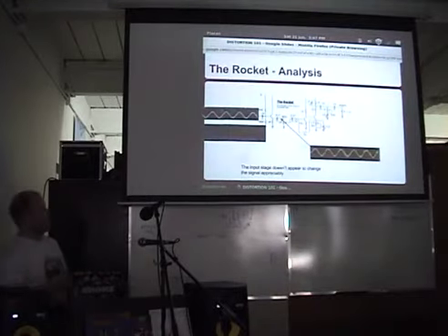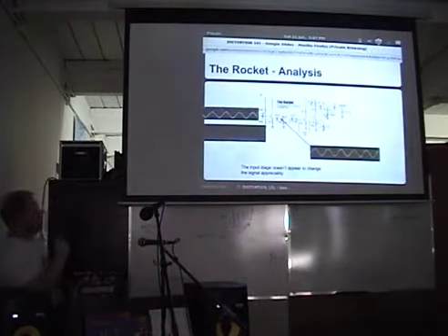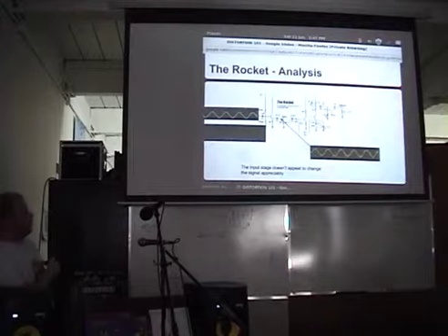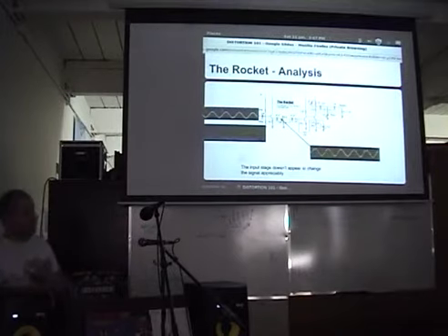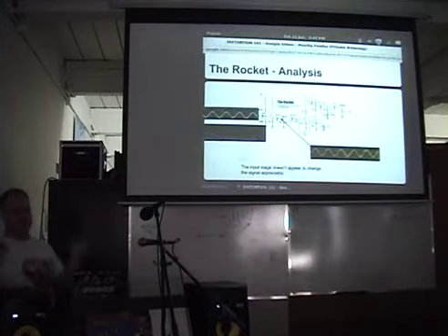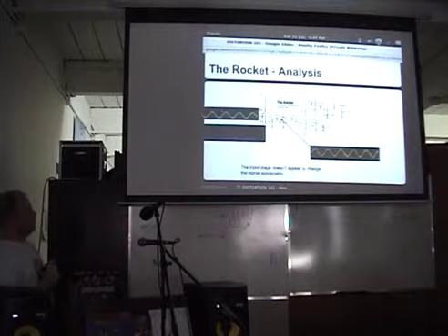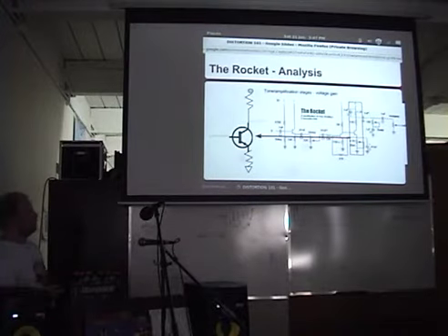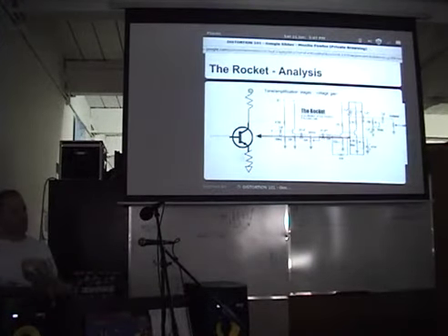So here I put an input signal from my rusty, trusty, and really sloppy signal generator to the input, and I measured the output of the input stage. And you can see that it looks very nearly the same, save maybe some glitches, because it's sitting on my desk and there are fluorescent lights interfering. But at least in the time domain, you can see that it's not really changed a whole lot, which is what an input stage is supposed to do.